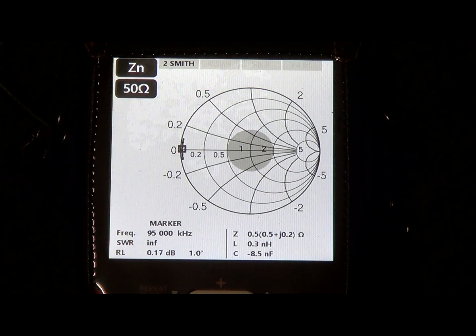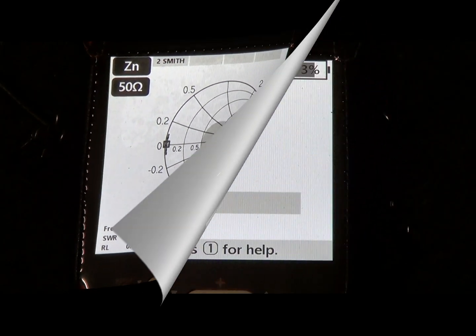Now the reason why it's showing it as a quarter wave stub, it's actually displaying as a half a wavelength, because what it's doing is sweeping down the length and coming back again, which is indicating 180 degrees, and anything, as I said, that is 180 degrees will cancel out. So you've got to use a bit of thinking there, and you'd better work it out if you just understand that the cancellation takes place with two portions of 90 degrees. And two portions of 90 degrees is 180 degrees, which is a half a wavelength.